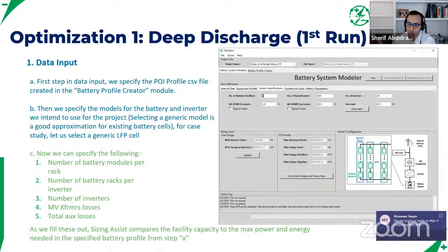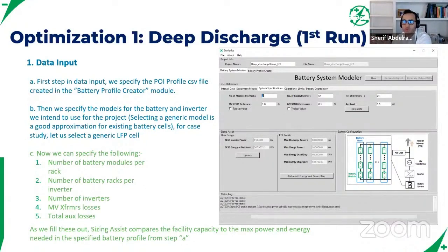So there's a lot of inverters out there that are basically multiple inverters within a single inverter. So they have multiple DC buses. That makes life easier in a way, but they are, in most cases, more expensive on a dollar per kW standpoint. So pick your poison. All right, but really good question. Thanks, Wes, for that.